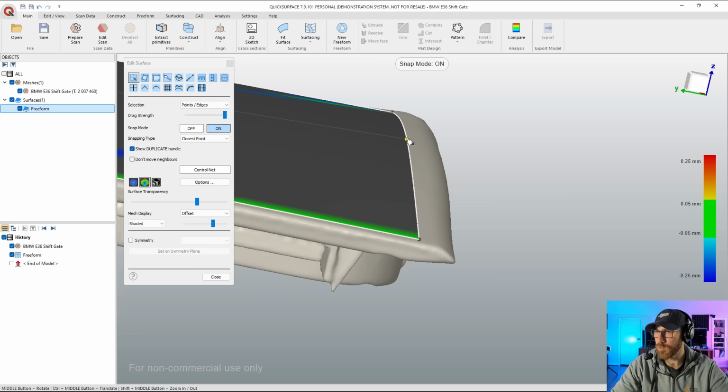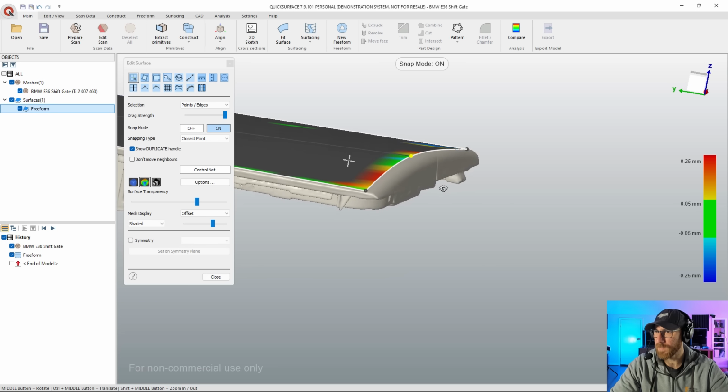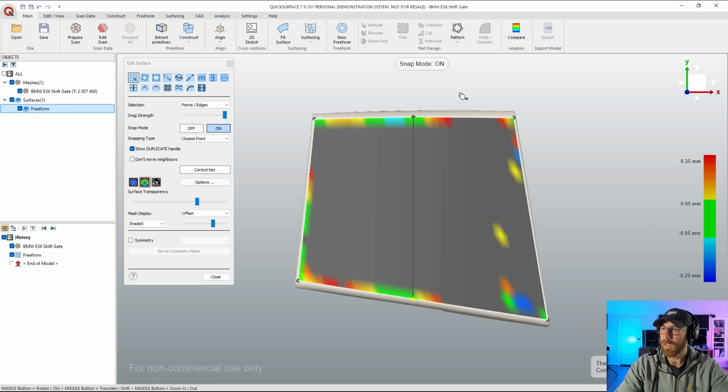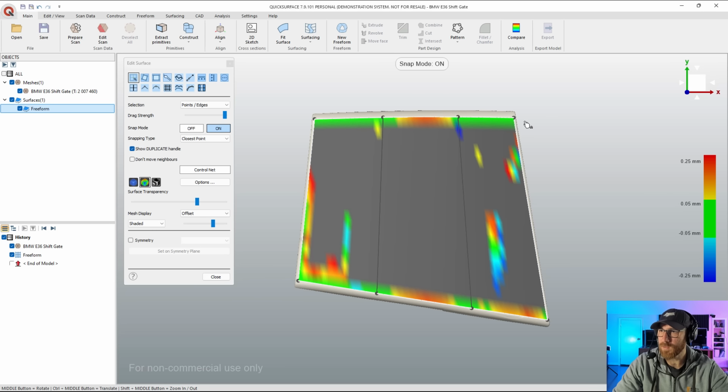So what we want to do is drag that back up top and see where it goes. Now, if I go back to a top view, you can do this from up here, and I was told a pretty cool trick: the way this works is it will snap based on the closest mesh point in our view. So it doesn't matter if it was snapped to the bottom edge, because we're viewing it from the top, it'll use that as its closest orientation. So we're going to do this again, hit S, and I'm going to hit S one more time.